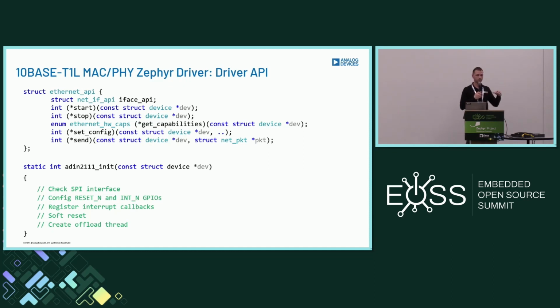So a common approach within Zephyr Ethernet drivers is to create dedicated threads in the driver layer which will be responsible for handling data received over the physical layer. These threads will be synchronized on interrupts from the device, which will then allow the thread to go ahead and read data from the receiving FIFOs. Okay.